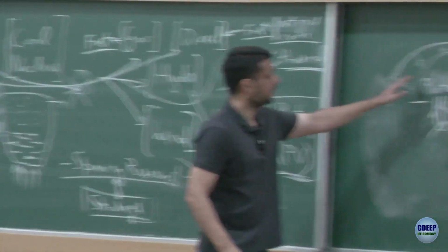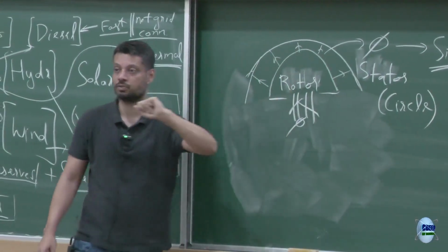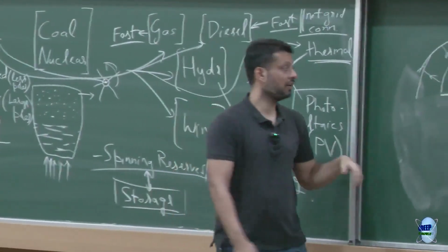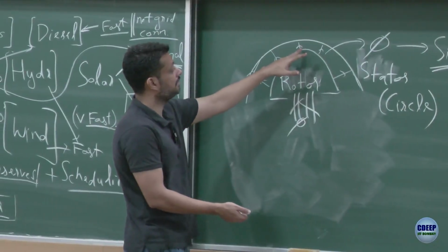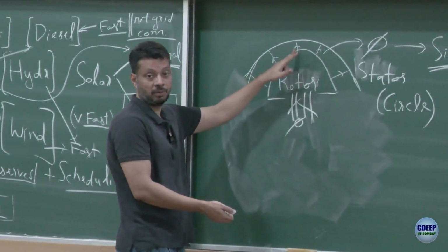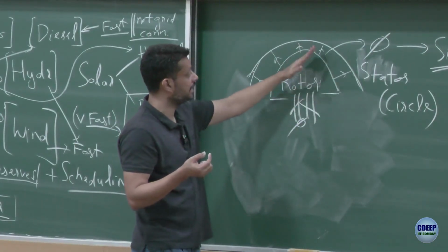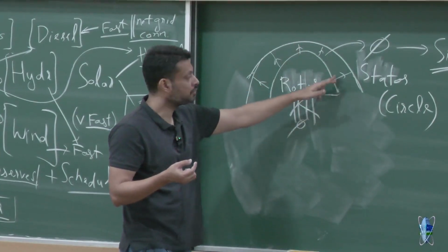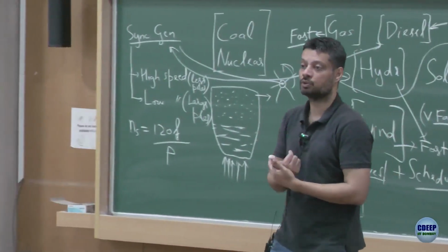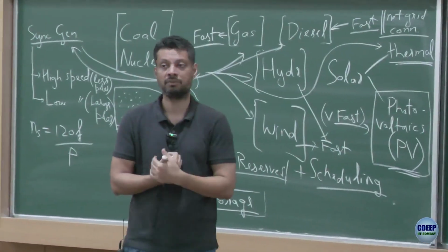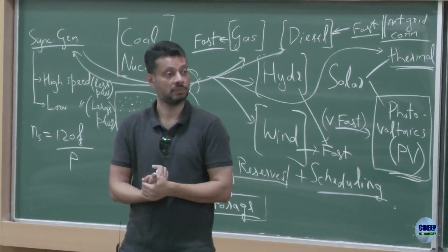By shaping this rotor, you can have a variable air gap and you can create a sinusoidal flux distribution, right. And now if this rotor rotates, it is non-uniform. Here if it rotates, you will have a lot of flux lines coming from right to left in a theta degree rotation. But if this point comes vertical and now you are rotating the same theta, only a small amount of flux will change, right. So therefore you can get the sinusoidal induced voltage instead of a square wave one which we got earlier. Is that okay?